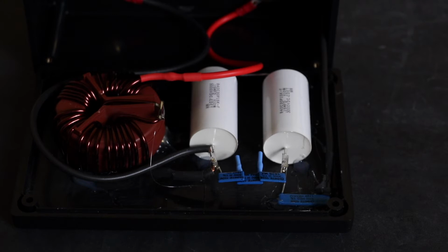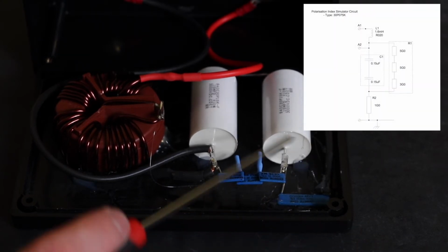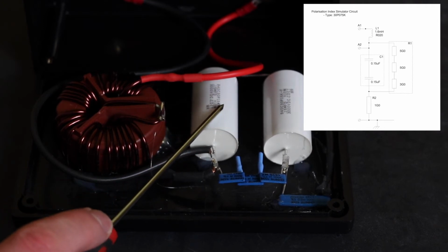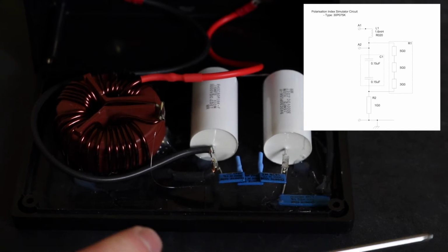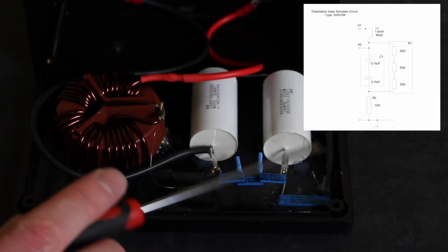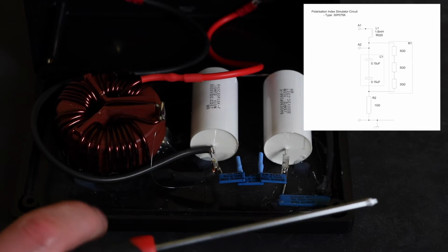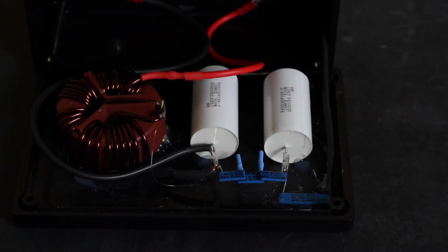So the RC circuit is this part built in down here. This is the C1, which is made up of 2 capacitors, and this is my R1, which is actually 3 resistors, and then R2 is just on the bottom here, gives the RC time constant with the capacitors. I try and keep the RC constant somewhere between about 80 to 120.